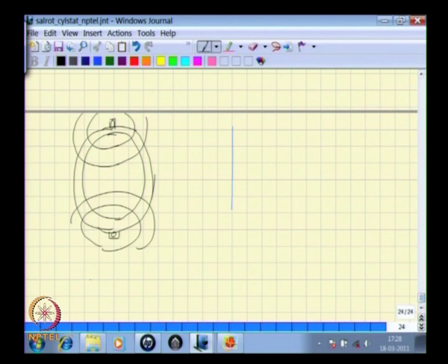If you go around any one of these loops, then you will have Hg into Lg. Let us say we are looking at the d axis MMF. So Lgd, or if we look at the actual MMF itself, Hg into Lg, and 2 times, there is one Hg into Lg dropping here, another Hg into Lg here.